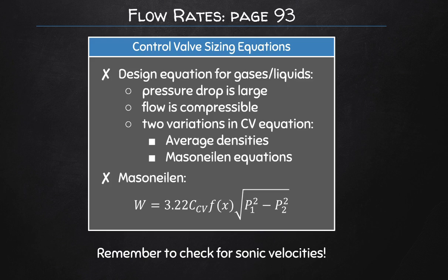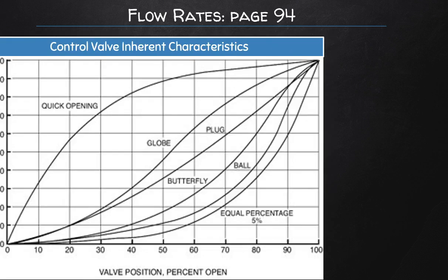So remember, we design control valves so that they are still able to control at the normal flow rate, and so the design flow rate must be used initially in these calculations when we are introducing them to the mechanical energy balance, but we'll get into this now.